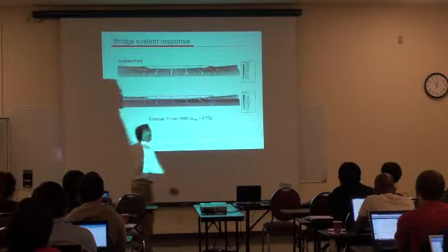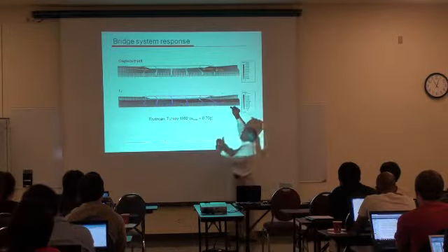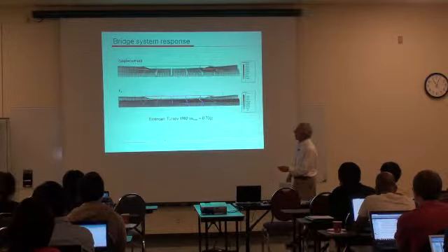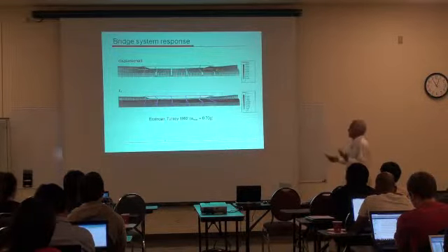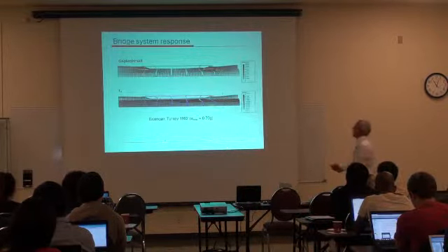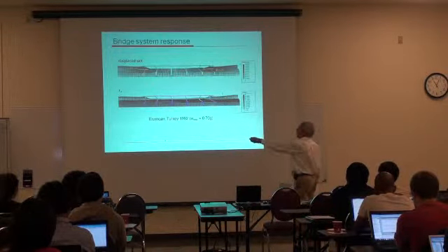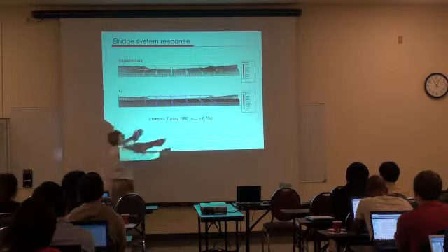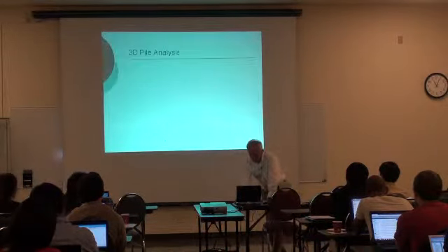So you say, oh, all the action is happening here. Well, because of how the pile was pushed and how it was connected to the other abutments, most of the maximum demands were on that side. So you could capture that only using a complete two-dimensional analysis of the whole bridge. If I had modeled only what happens here, I would not have obtained the maximum demands, because the maximum demands were on the other side. And if I had done only the analysis here, I would not have captured the effect of the other side. That's a situation where a 2D analysis becomes important.